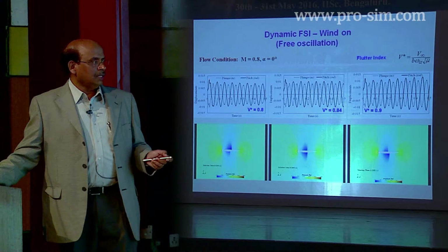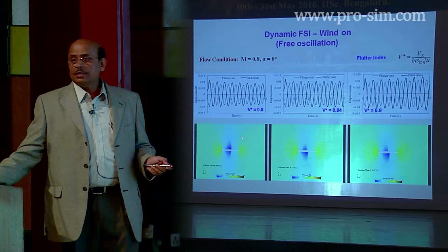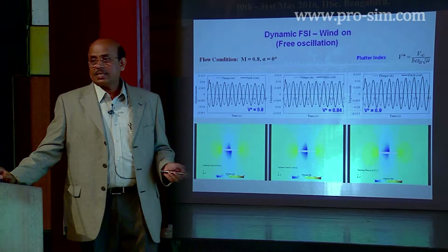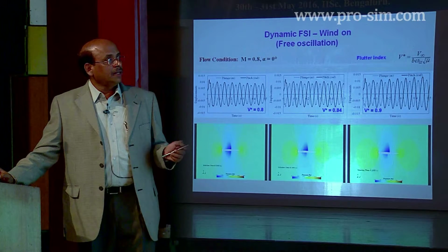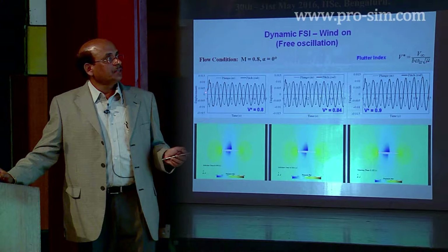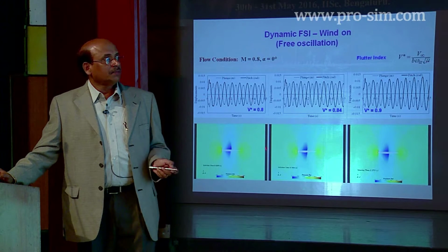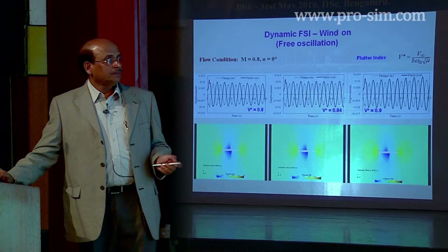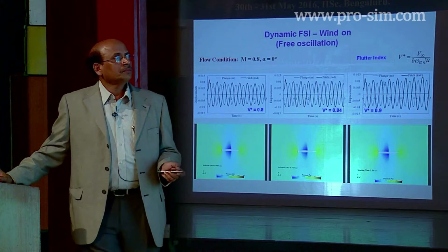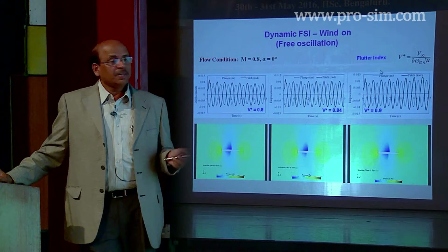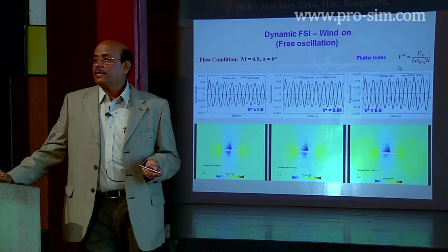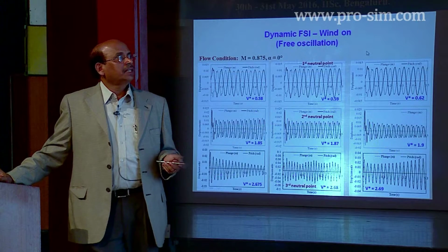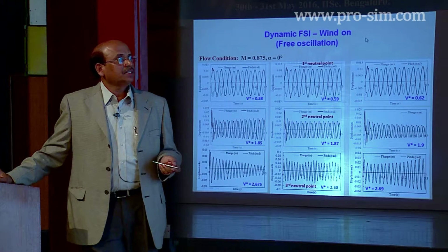Yeah. So this is the animation. What we are seeing is the fluid structure interaction animation. The fluid as well as the structural equations are being solved simultaneously, and the end product is the displacement time history of the airfoil. This is done at different Mach numbers, and ultimately from the displacement time history we calculate what are known as the flutter indices. It is again a repetition of the same thing for different Mach number conditions.